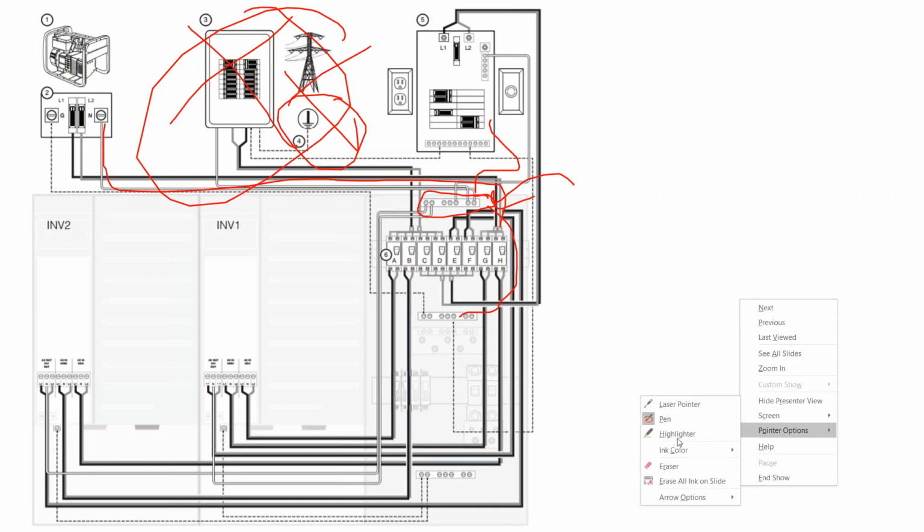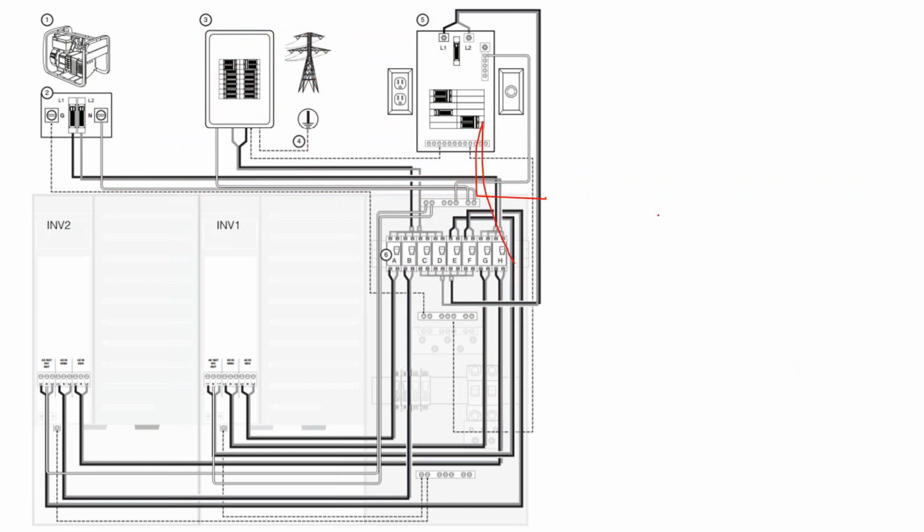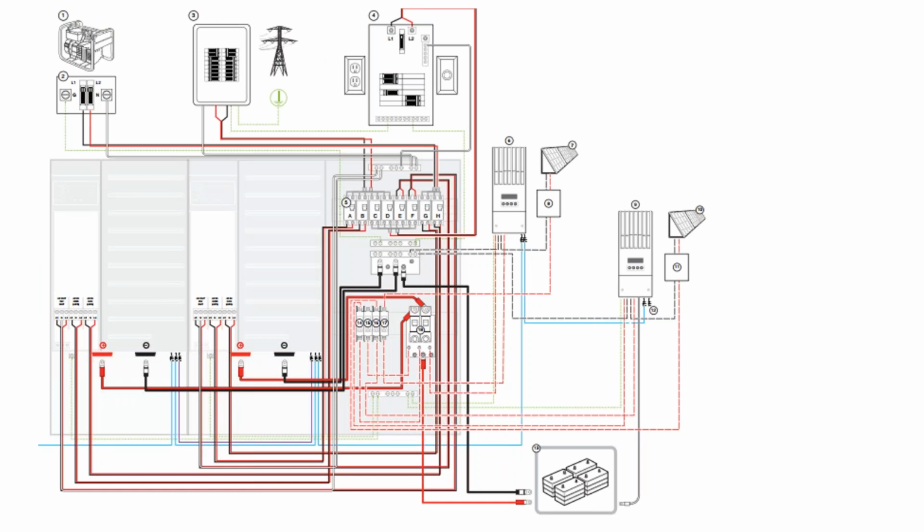You get a lot of different wiring diagrams from the manufacturer to accommodate a wide variety of design scenarios, but not everything is going to be straightforward. You've got to rely on your electrical knowledge to say, hey, can I actually double lug onto a shunt? Hey, the plans don't specify where I'm connecting neutral to ground, but I know there has to be one neutral to ground connection. So where does that occur? You have to rely on your general field knowledge or electrical knowledge for that.